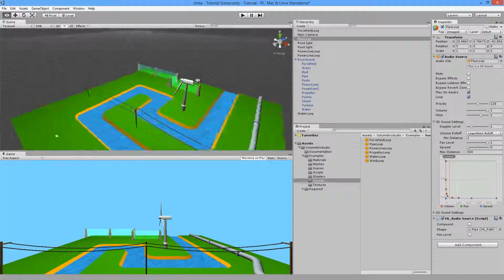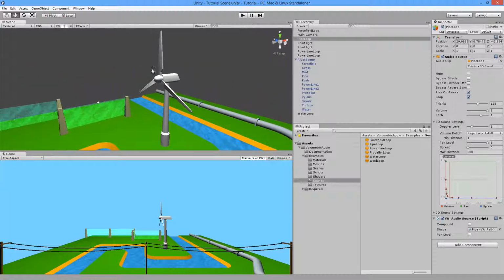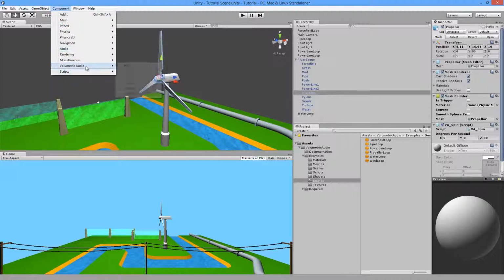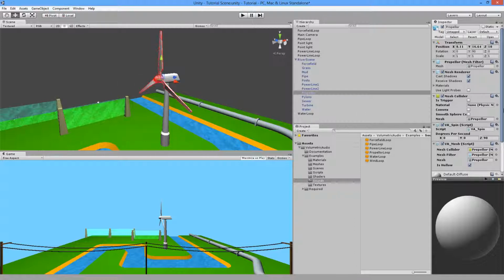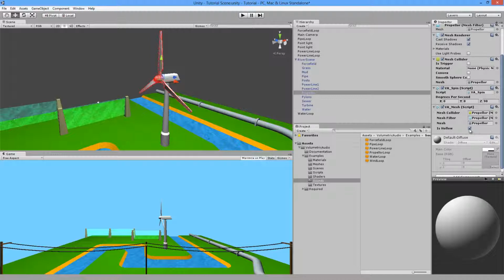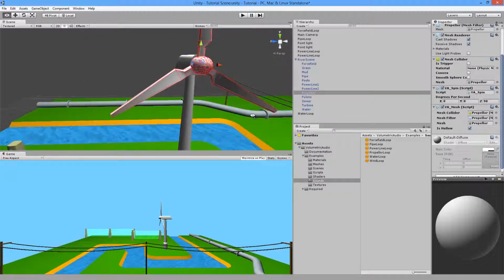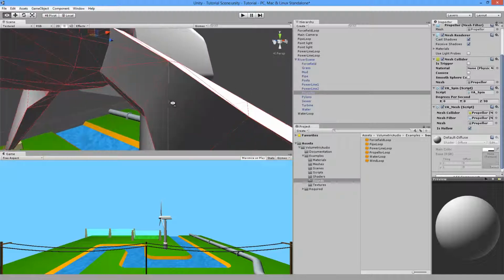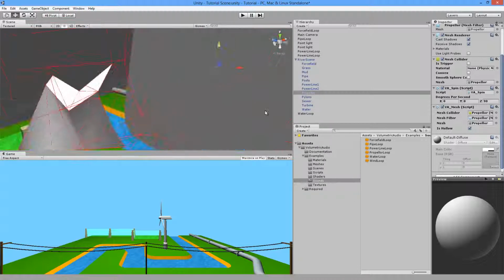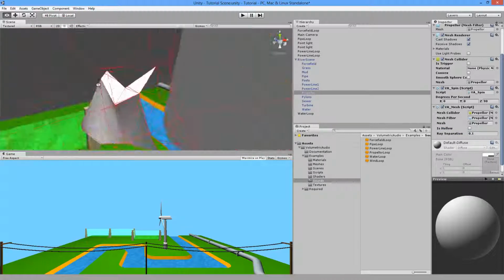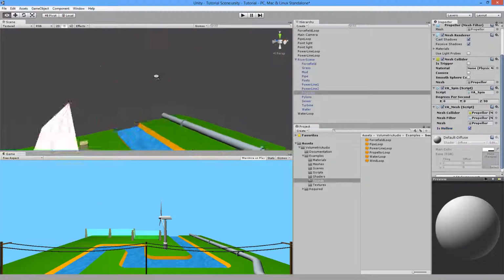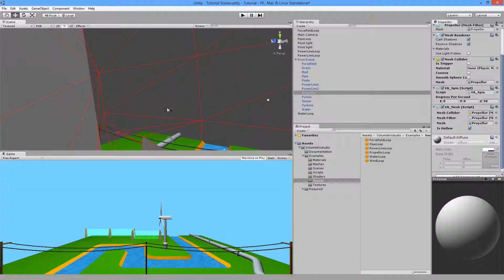So now let's move on to some interesting stuff like the propeller. Let's begin by selecting the propeller blades, and let's add, like we have done before, the mesh component here. Again, everything's been filled in. If you're wondering what the is hollow setting does, that allows you to change how the sound is treated when you enter the mesh. In this case, if we wanted a sound to come from inside the propeller blade itself, then we would uncheck this, and when the camera enters it, we would suddenly be surrounded by sound. If you leave it as is hollow, then sound would only appear to come from the skin or the surface